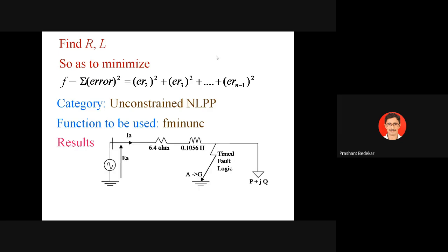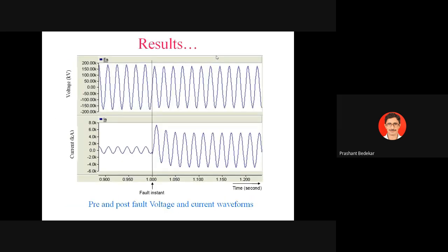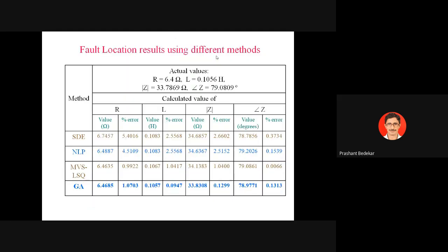Just for comparison of the result, I have taken fixed values of resistance and inductance. Using PSCAD, I have got the current and voltage samples after creating the fault. Then I have applied different algorithms, calculated the values of resistance and inductance, and found the percentage error.